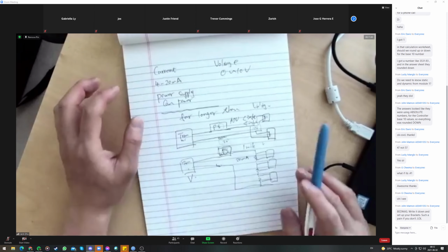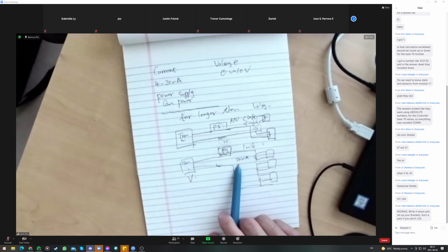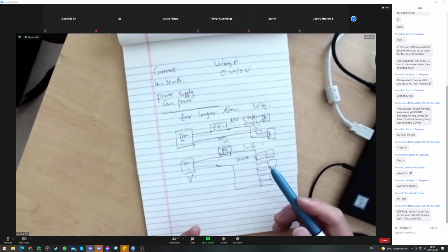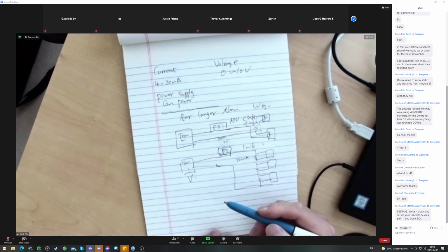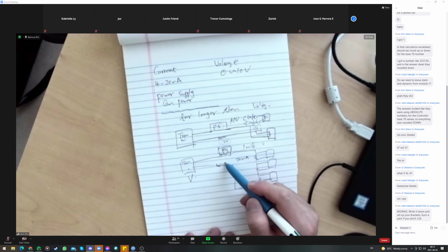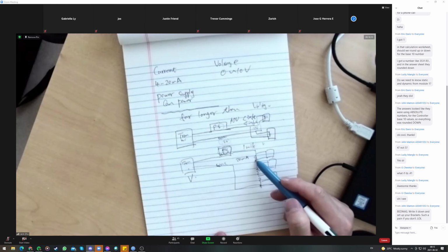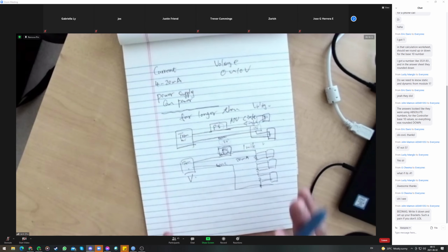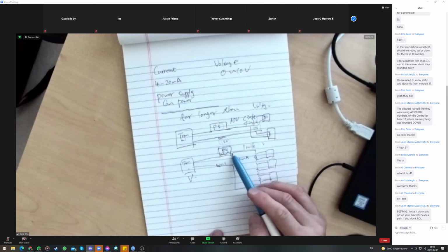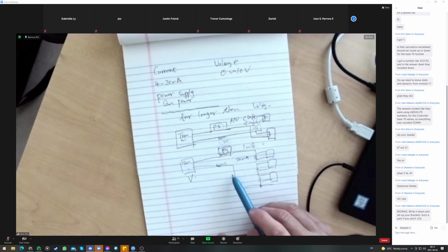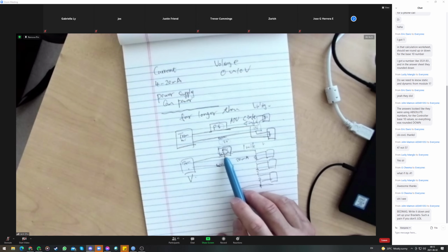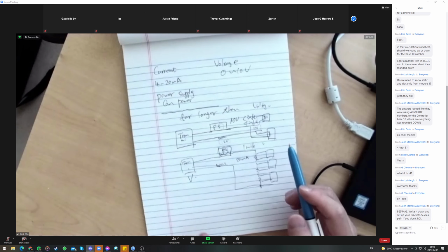But at the same time, because you need that 20 milliamps, if your distance goes really long, your wire size matters. It is control wire, right? You're not going to use very large size control wire. So if you want to add some extra equipment or have voltage drop down here, like the example we did the calculation on yesterday, with all those calculations to find the voltage drop, it's sometimes hard to find a power supply that will be able to give you the voltage you require.